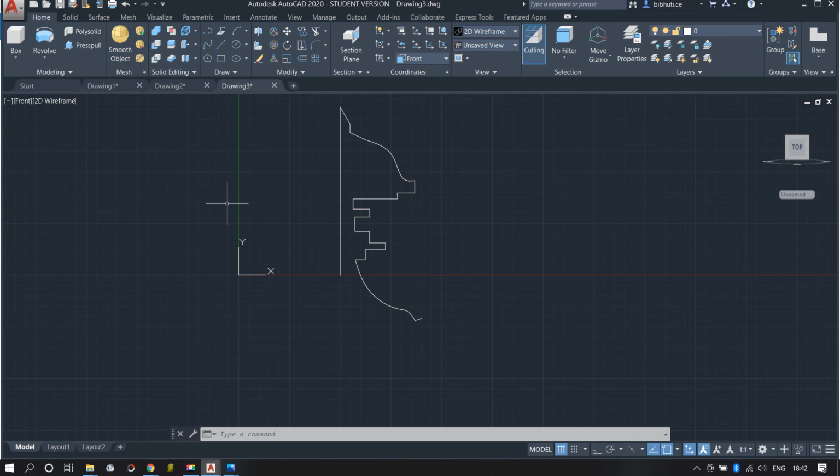The thickness will be whatever thickness you want. Then you revolve, then you will be able to convert it to an STL file. Otherwise you will not be able to, because the surface that was created doesn't have any kind of thickness. That's the problem.